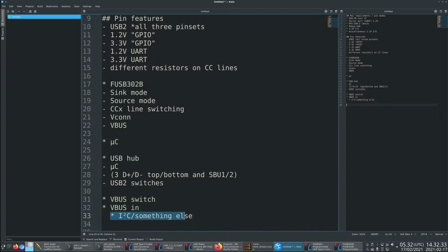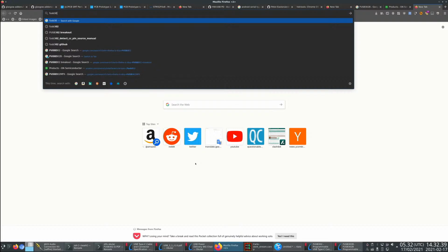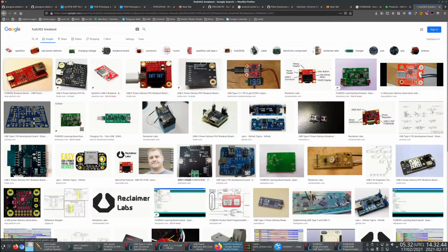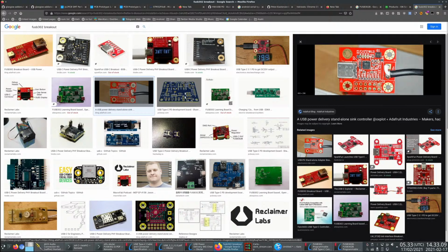It's just we need to have some connector on the board. This is, by the way, the reason why I'm doing this like this: if you look up FUSB302 breakout on the internet, and you would think people have already built these things, you get stuff like this. This is a FUSB302 connected to a Type-C connector with the USB 2 lines passed through, and nothing else. There's VBus, but where are the SBU lines? Where are the high-speed lines? You have this board, and you're just throwing away all these pins that don't go anywhere. Or things like this, and this is one that has an actual chip, I think. Or there's one that has...